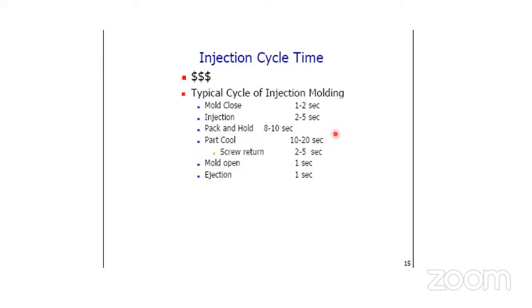Part cooling. Cooling takes the maximum time. See, same as in the case of compression and transfer molding process: 10 to 20 seconds, the highest time.